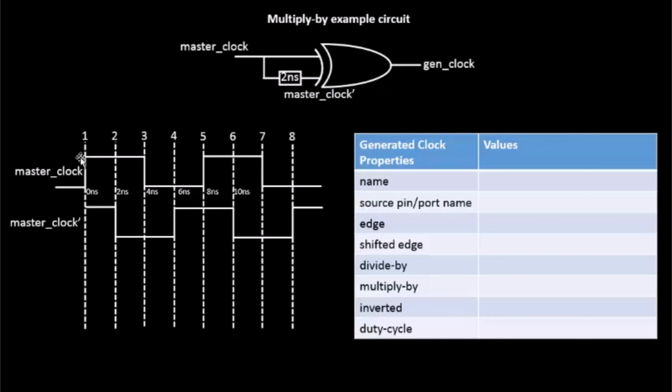Now the XOR: 1 XOR 1 is 0, and 1 XOR 0 is 1. Basically, unequal inputs at the XOR gate create a logic 1, and same inputs create a logic 0. So if you have similar inputs at the input of the XOR gate, the output is 0. So let's draw it.